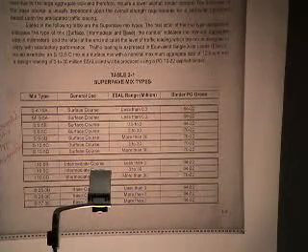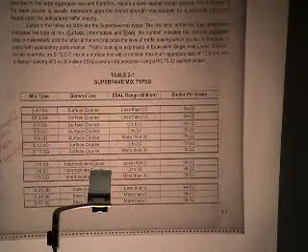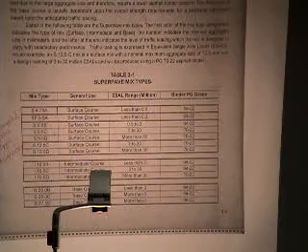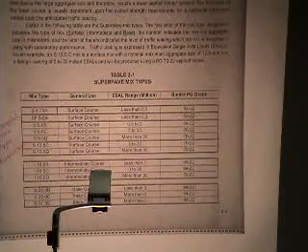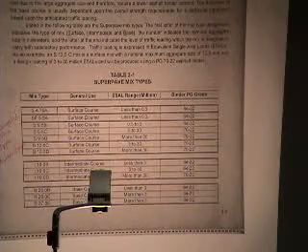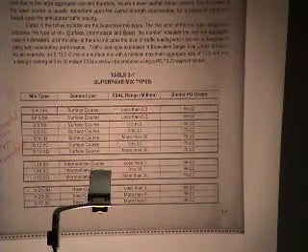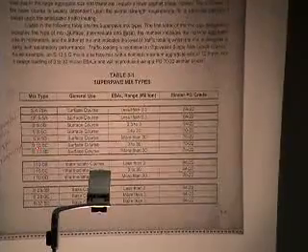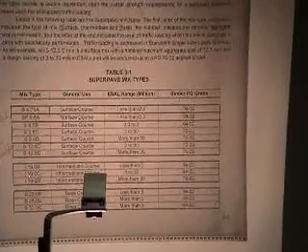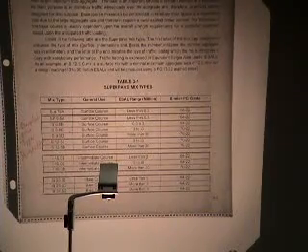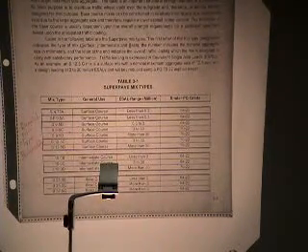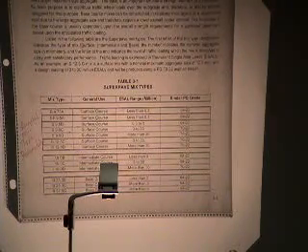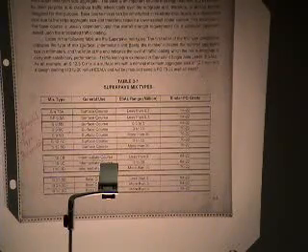Now why they're in millimeters, I'm not sure. The only reason I've ever come up with was because when Superpave was being developed, metric was the going thing, so they designated these aggregate sizes in millimeters. But just to give you a feel, if you're not metrically inclined, and neither am I, 9.5 millimeters is about 3/8 of an inch. 12.5 is about 1/2 an inch. 19 is about 3/4, and 25 is about an inch. So as you see, it makes sense that the surface mixes have the smaller top size aggregate, intermediate is in between, and then the base mixes have the largest coarse aggregate.